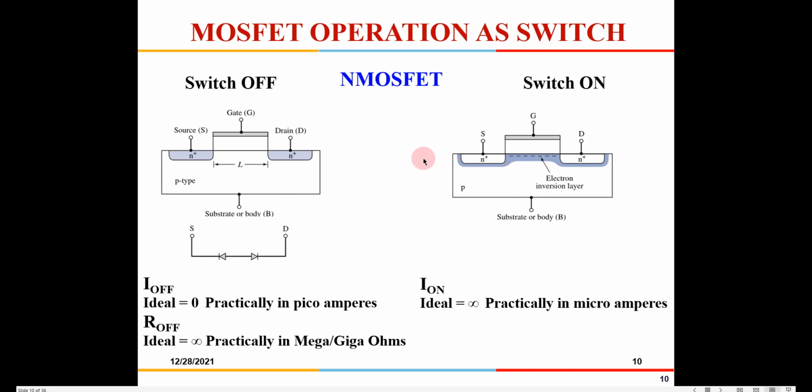And if there is a capacitor, generally you will find a capacitor connected to the other terminal of the MOSFET. That capacitor will slowly get charged through the ID flowing in this device, so you can't call this an ideal switch. The capacitor will slowly get charged to VDD, and as the capacitor keeps getting charged at the output, the VDS also keeps decreasing, right?